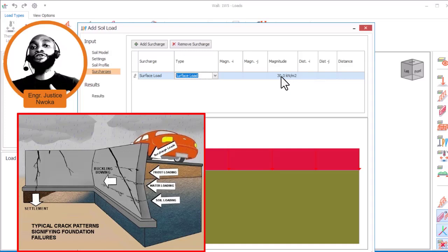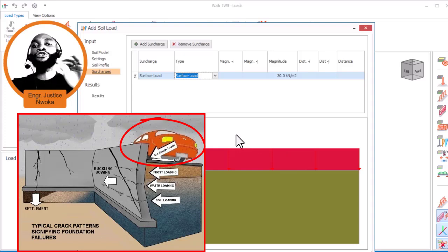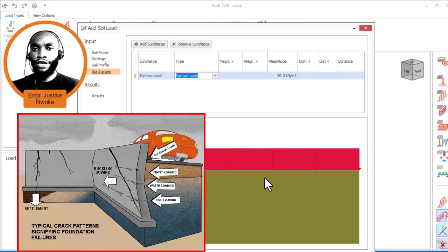So now you know that among all these types of load, the maximum load that can pass through the soil around the perimeter of a basement wall or retaining wall is the vehicle, because that's the maximum among all the loads I have just mentioned: human load, bicycle load, someone driving a bike, motorcycle, and then the vehicle. Knowing that we design for the worst condition, we are going to deal with the vehicular load.